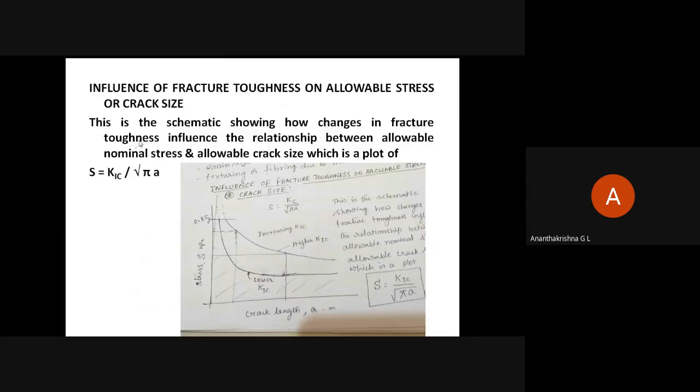Okay, so this is the one, no? Yes, sir. So three stresses: S1 is greater than S2 greater than S3. All the specimens contained the same crack length, and the number of cycles for higher stress is less. So fatigue crack growth was larger in higher stress specimens. Okay, this is what we learned.